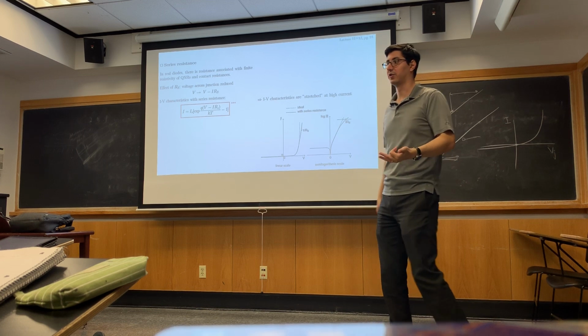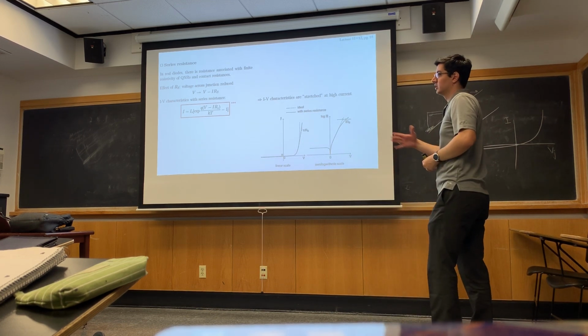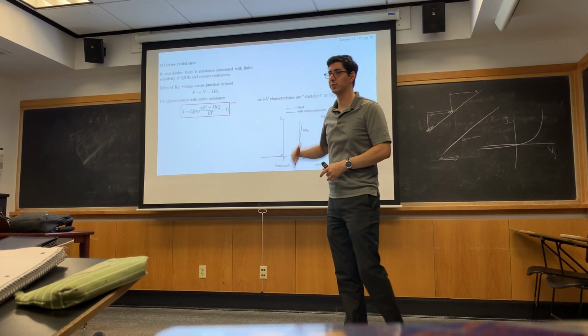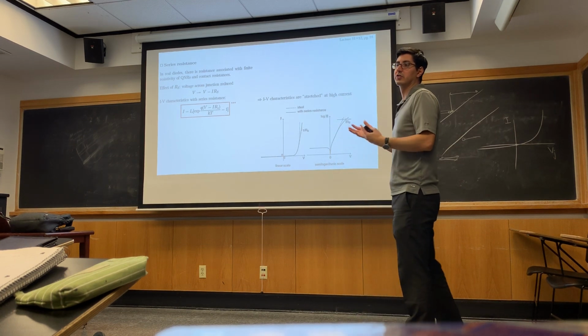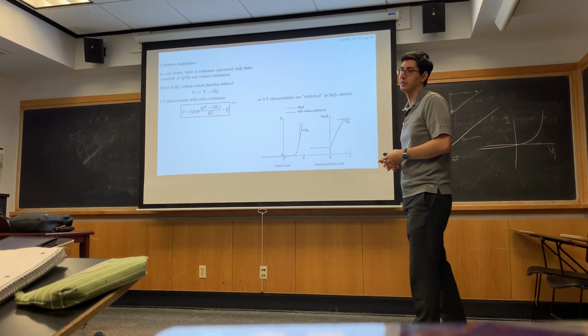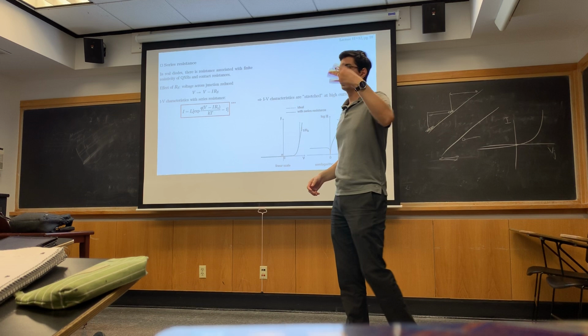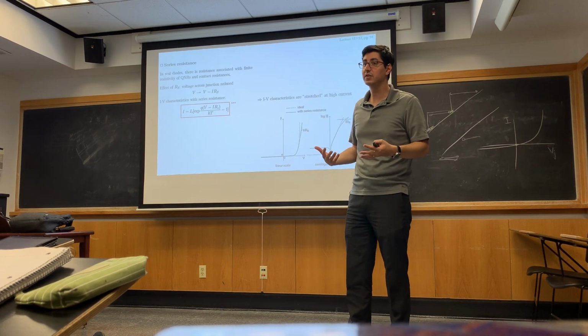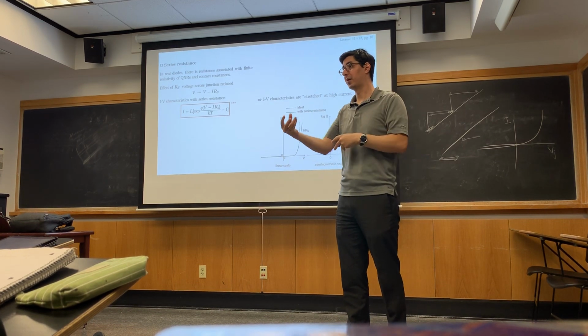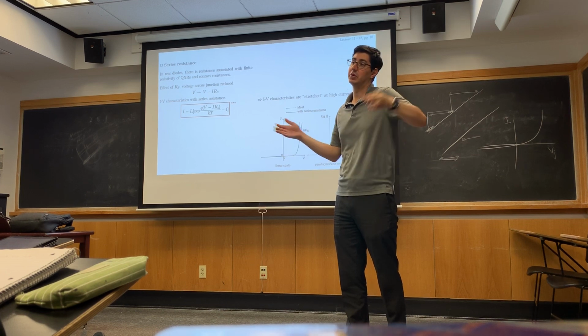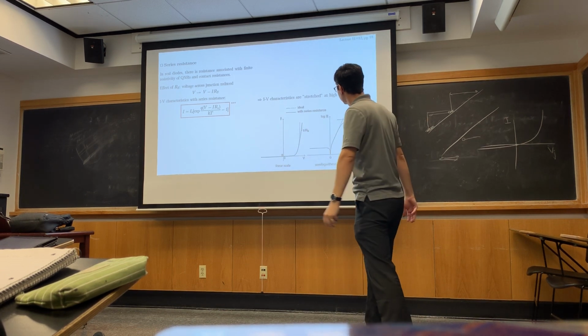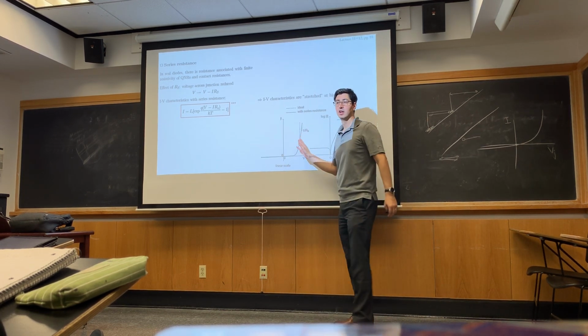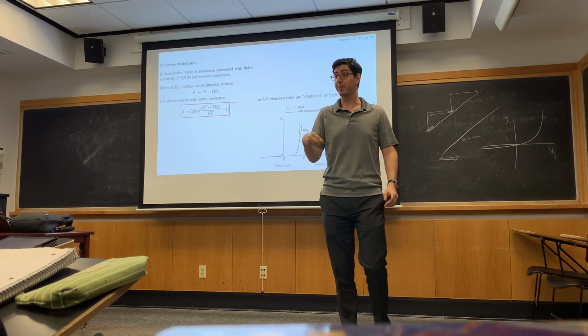You can think about that. If I had a really large resistance, then I change my voltage a lot, and my current is very small. Okay, so initially my junction is very resistive. So even if my quasi-neutral regions have some finite resistance, probably my junction overwhelms it, and we can just ignore them. But in strong forward bias, my junction resistance is dropping very, very quickly.